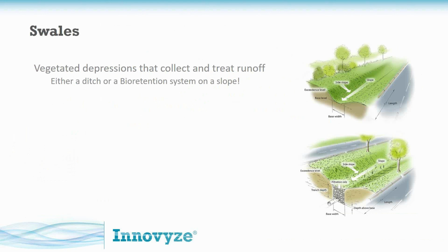So you see in the lower right, that image is showing a swale where someone has excavated out the base and put in some sort of infill so that the water can drain down through it. That can obviously treat your water quality event, but if you can kind of anchor that sediment where it is with fabric, what have you, well, that can also be your kind of high flow drainage corridor.